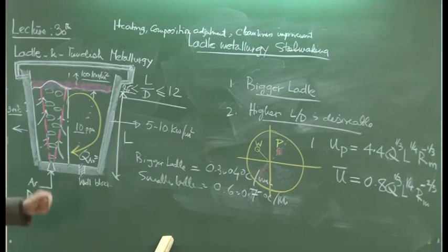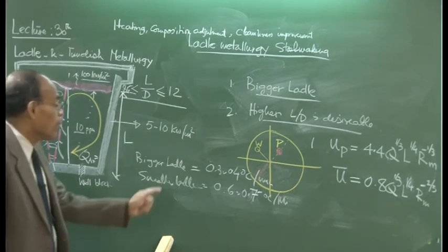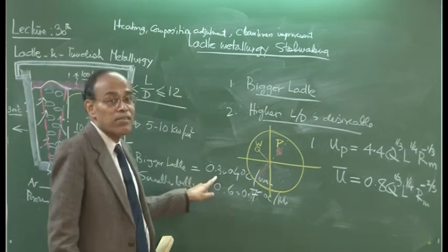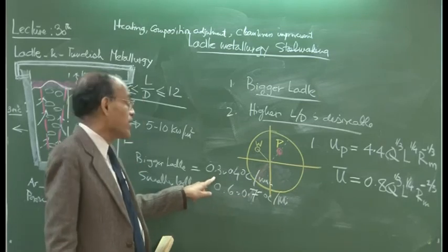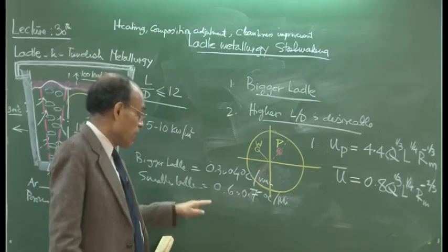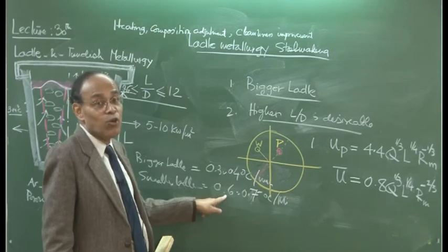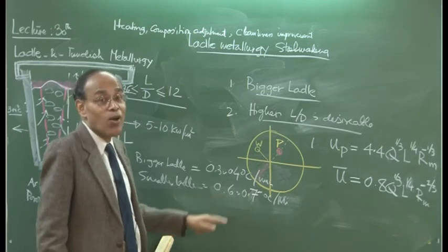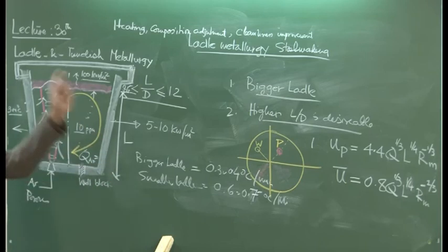So, continuous heat loss is taking place. If you are processing for 70 minutes, you have a 21 degrees centigrade heat loss, and similarly here about 42 degrees centigrade heat loss. And you have already lost 70 degrees in the ladle during the tapping process itself.